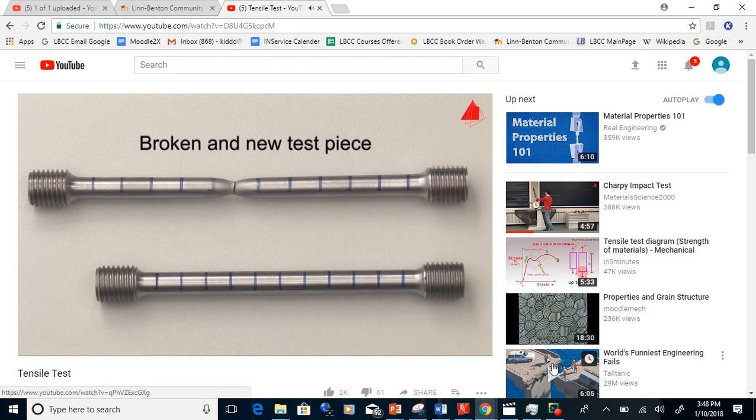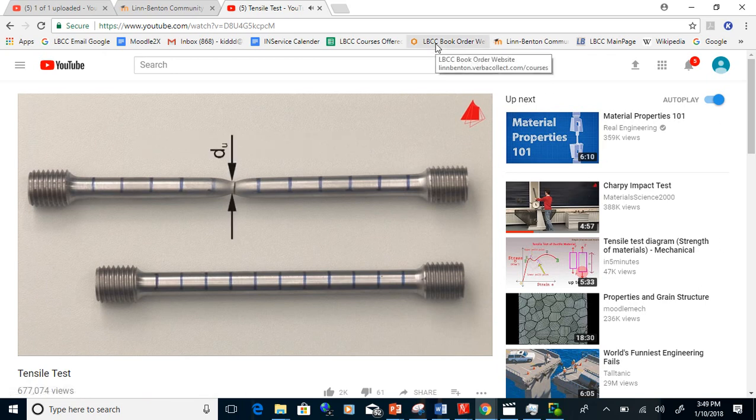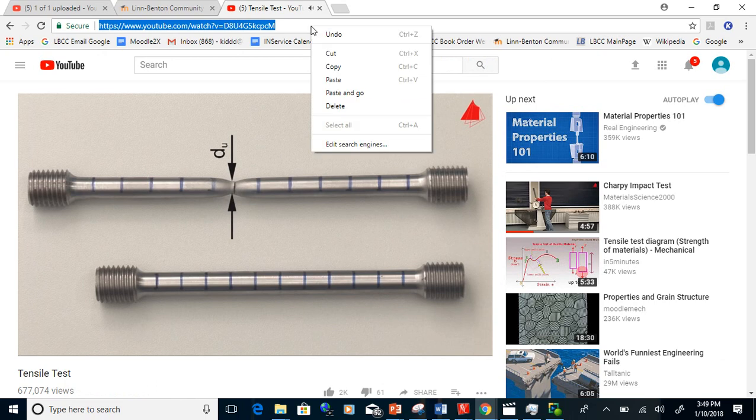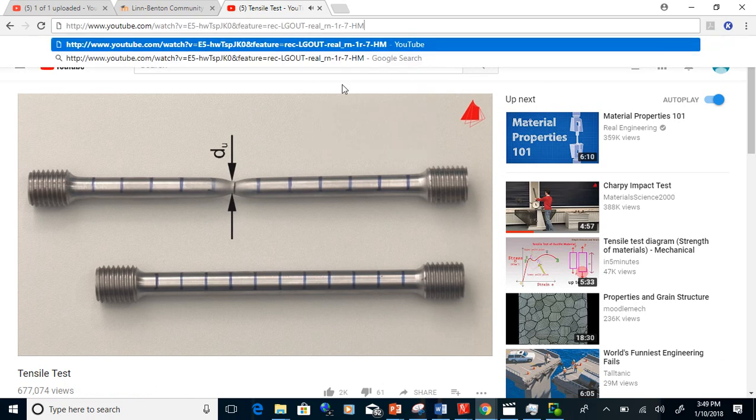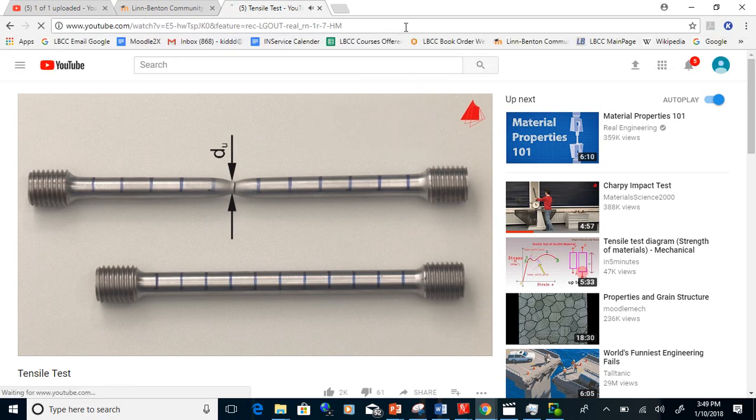Please note that the percentage elongation after fracture depends on the length to diameter ratio. By measuring the smallest diameter at the point of fracture, the percentage reduction of area can be calculated. It describes the reduction of cross-sectional area at the point of fracture in relation to the...